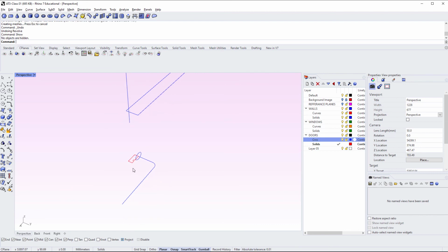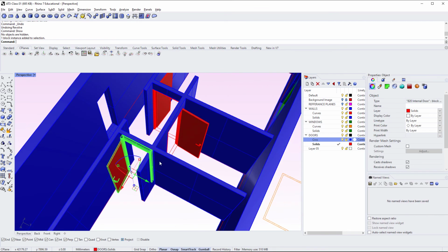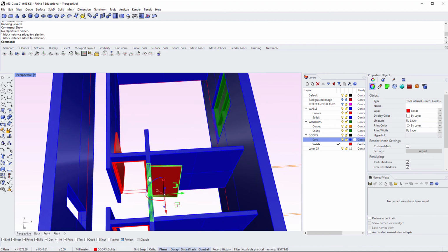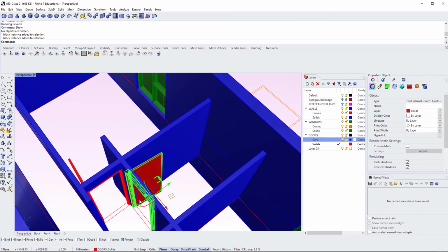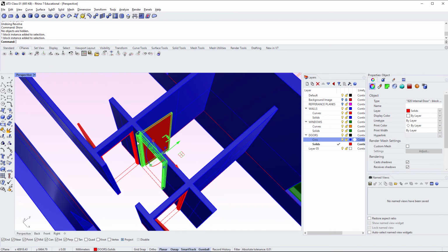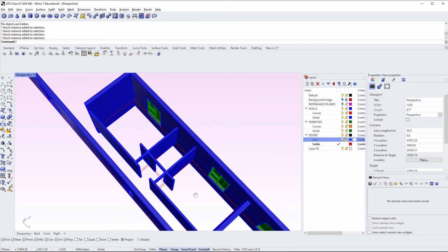So with that now complete, those internal doors complete, it's up to you to take that same method and apply them to all the internal doors. Now, if you want to keep some doors shut and other doors open, that is fine, but just note you'd have to make 2 different blocks because the blocks are that the doors are open. So if I was to open this block up and edit it and close it, as soon as I save that block, all the other doors will also be closed. So just keep that in mind.